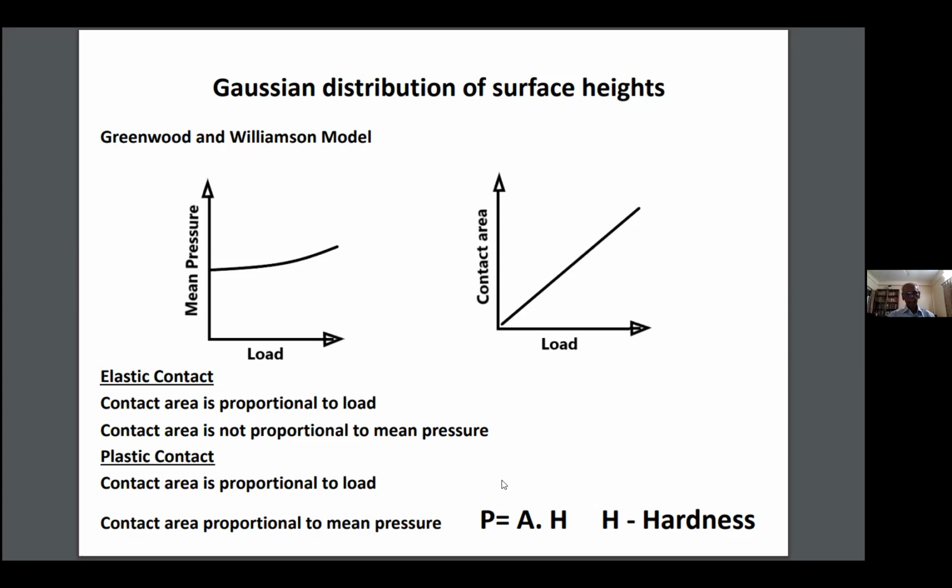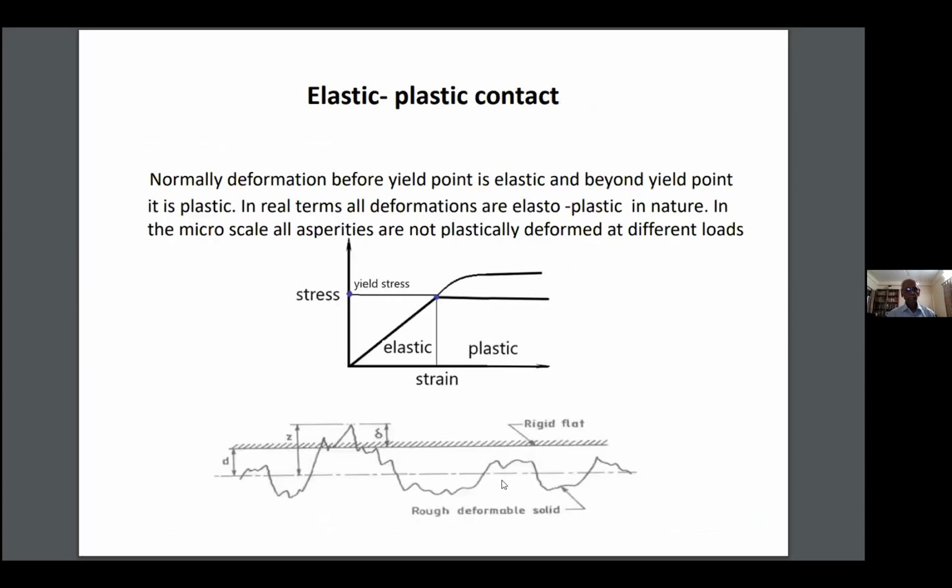But this remains the basis for all the further analysis, that for both elastic and plastic contact, the contact area is proportional to load, and the contact area is proportional to mean pressure. So this was a good understanding, but in order to do that, we had to understand Hertz theory and the Greenwood and Williamson model.